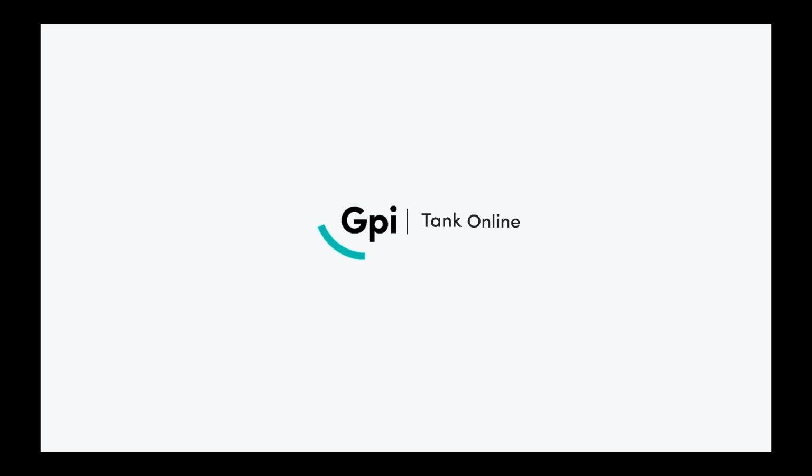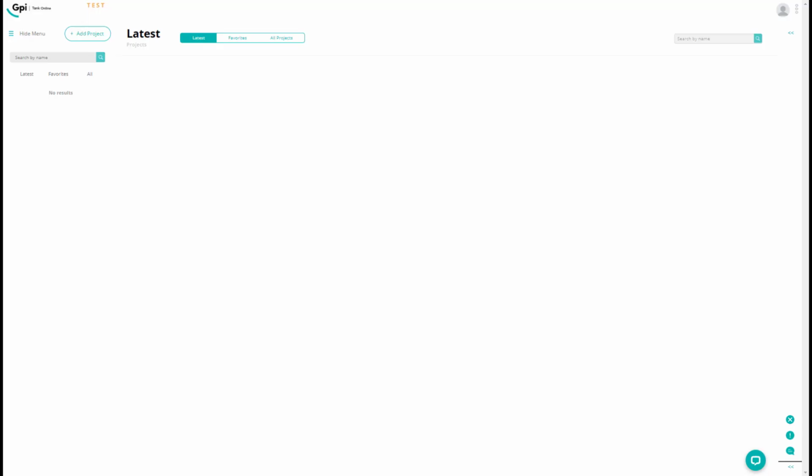Hi! Welcome! This video will guide you through the basic process of designing a tank. The workflow in the software is designed in such a way that tanks can be designed only within a project. Therefore, the first step is to create a project. To do that, click on the button which reads Add Project.